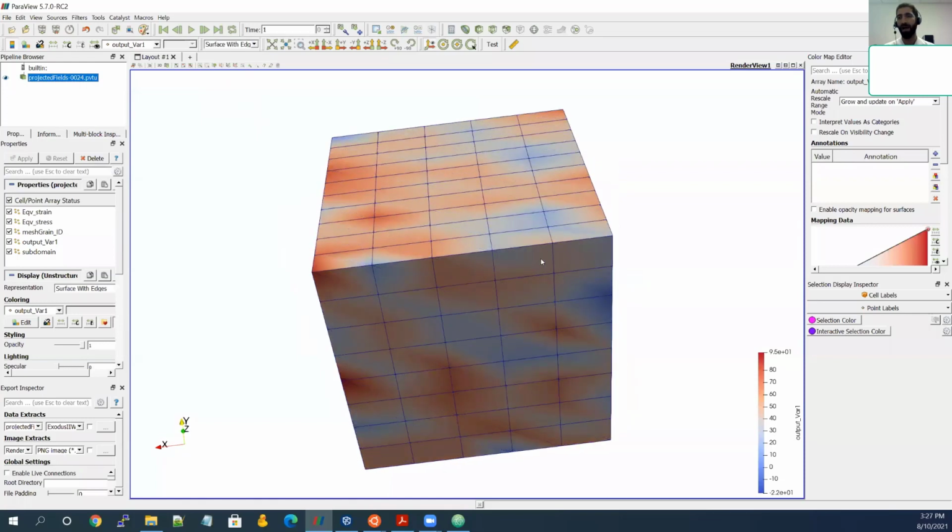This is how you add an extra variable to your post-processing, if it's not a default variable. But still, if it's some statistical analysis besides visualization, you can always use Quadrature output because it will give you the precise value at the integration point. This is the post-process value prepared for ParaView by inverse solving that linear equation.